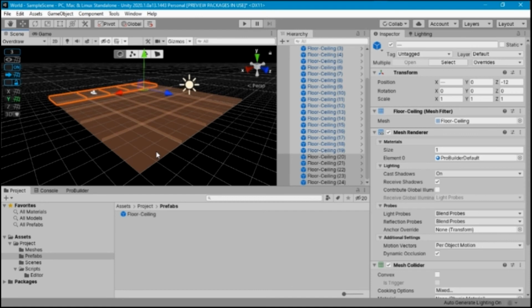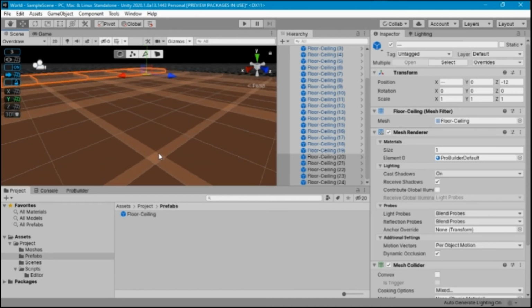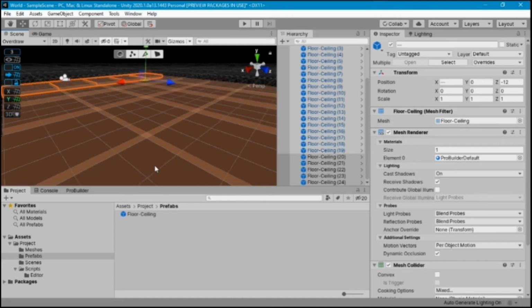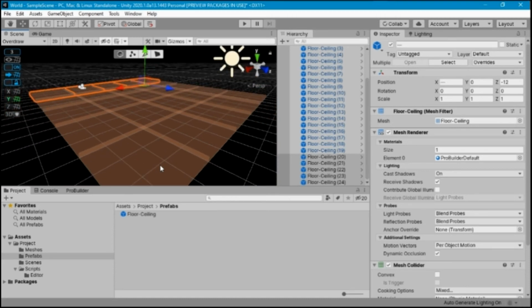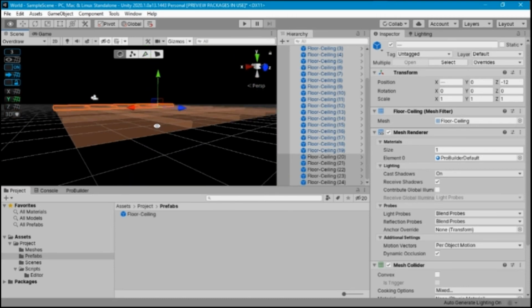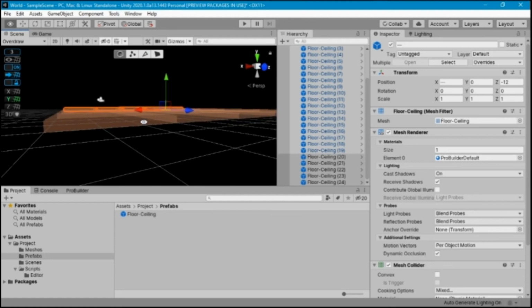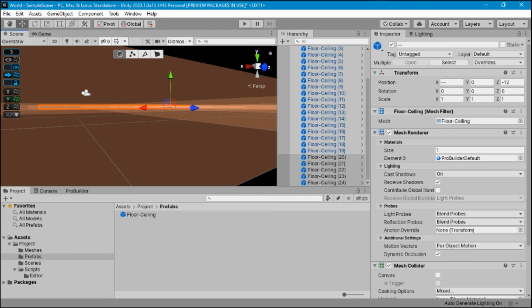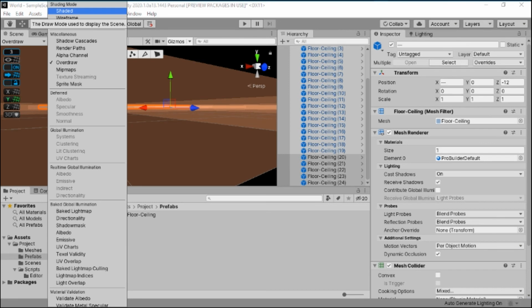In a closer look, it's obvious that some areas are being drawn up to 3 times every frame, which is inefficient. From this perspective, this is a small problem, but if we move the camera to another position, the overdraw level can grow dramatically. On the next episode, I'll teach you how to minimize overdraw while still using tiles. For now, we'll just finish creating our basic tiles. Please change the render mode back to shaded.